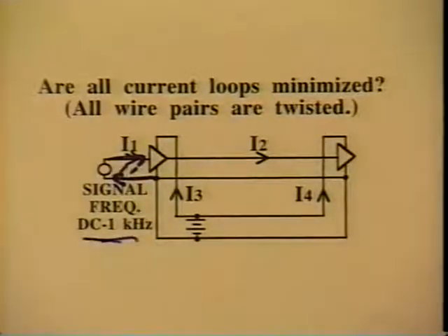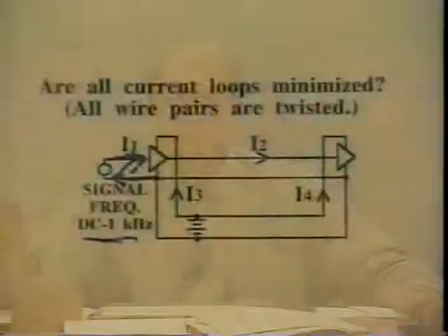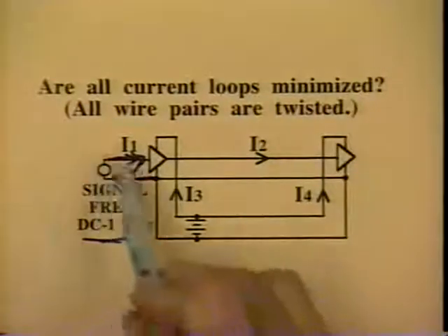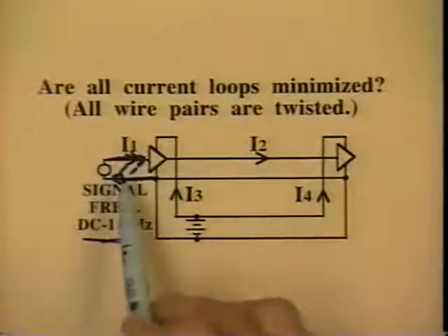This is low-frequency signal. Remember, if low-frequency signals have more than one path, they're going to use them. Low-frequency currents go everywhere they can possibly go, is basically what happens. And that's a real troubling situation. So the best way to handle low-frequency signals is only give them the one path over and the one path back that you intend for them to use. Don't give them any other opportunity. So we successfully accomplished that with this signal.